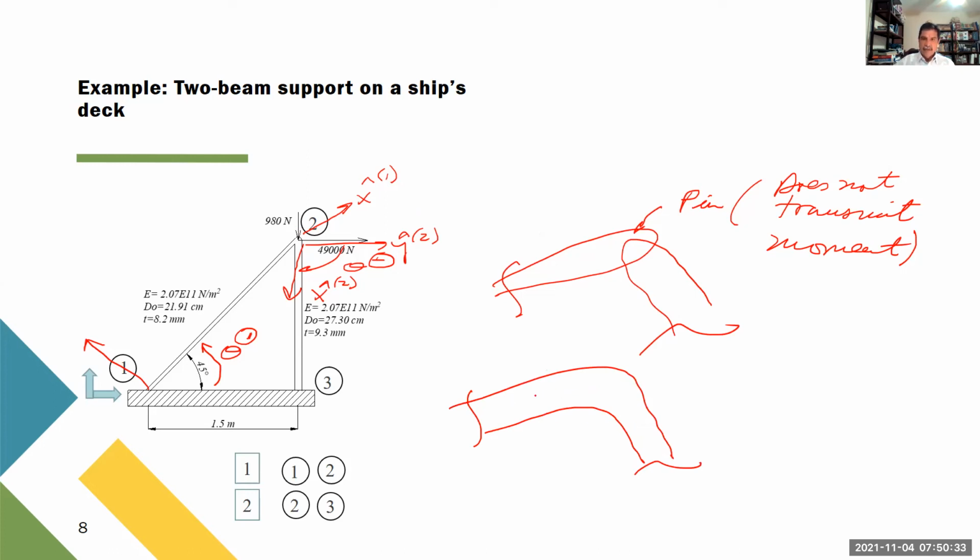So if this one here rotates, let's suppose this is the original direction. Let's suppose that this point rotates to this point. The other one, okay, they have to rotate in the same direction. So this has to come to this. But if this rotates and forces this one to take this angle, what do you have to transmit in order to make this rotate the same amount? You have to transmit moment.